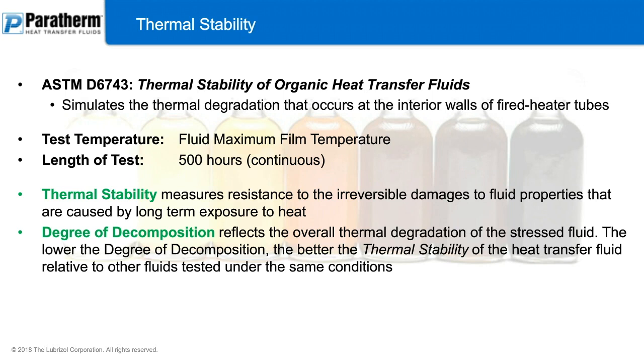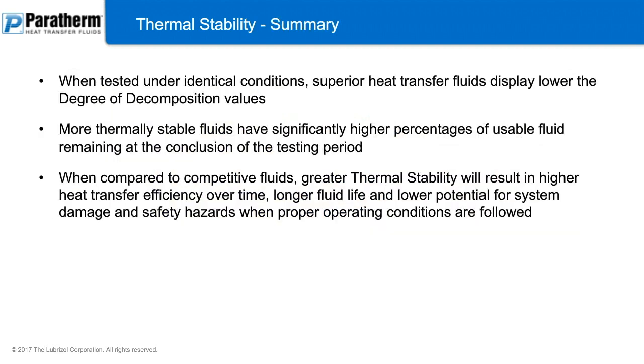How much fouling and how much degradation can you expect due to thermal breakdown? A fluid with higher stability will cause less of that. So really when you're looking at this, greater thermal stability fluids will result in higher heat transfer efficiency over time, longer fluid life, and lower potential for system damage and safety hazards when proper operating conditions are followed.